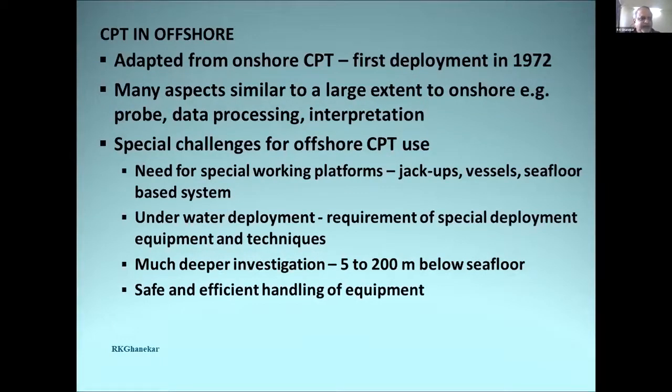Actually, in offshore, the CPT was adopted from the onshore practice, and the first deployment in offshore took place in 1972. Many aspects are similar to a large extent in onshore and offshore, like the probe, the data processing, and the interpretation. However, in offshore, there are special challenges for the use of CPT or CPTU. One is the need for special working platforms. Since we are working underwater, we need special platforms like jackups, vessels, or the seafloor-based systems.